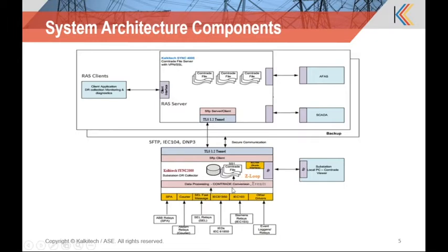We convert it into a Comtrade common format and push this file to the central system over secure FTP, and at the central system the automatic fault analysis system can do the analysis of the Comtrade files. Events are also collected from the relays, made into CSV format and then pushed on to the central system, and the AFAS tool can analyze the Comtrade, combining the events also.